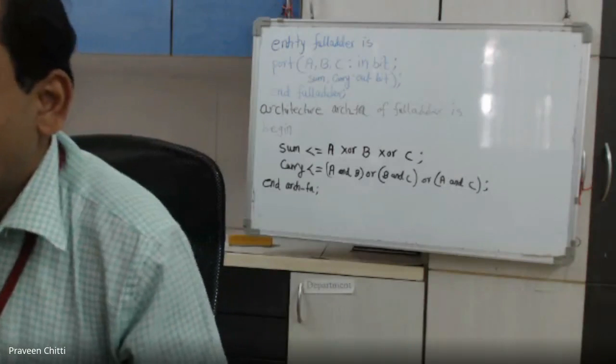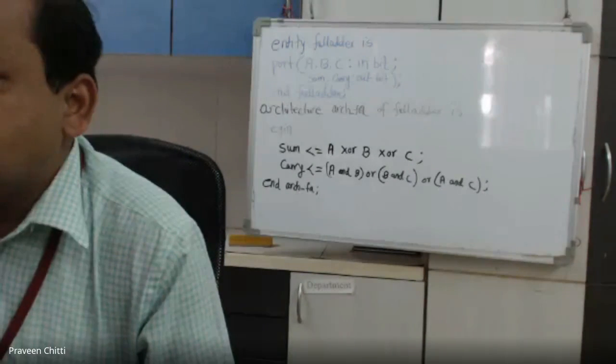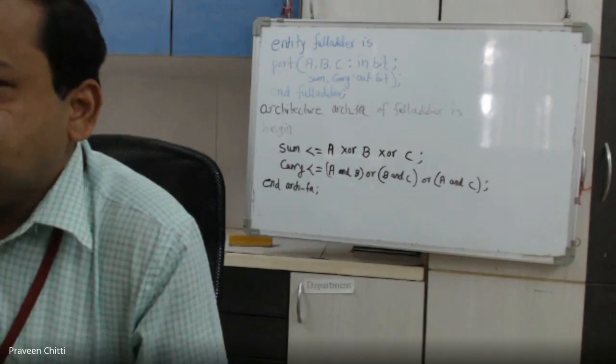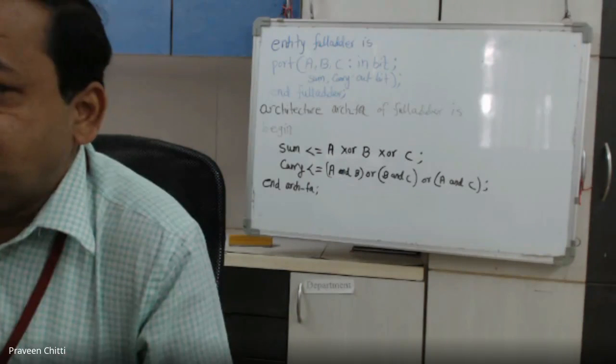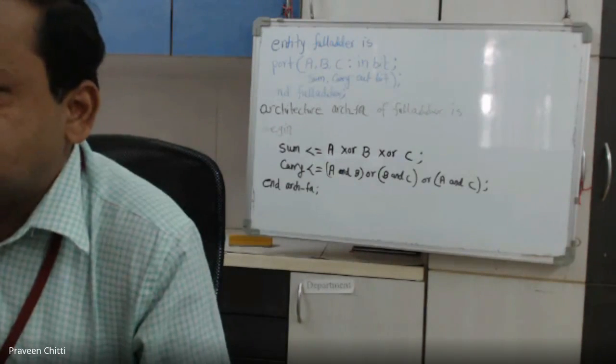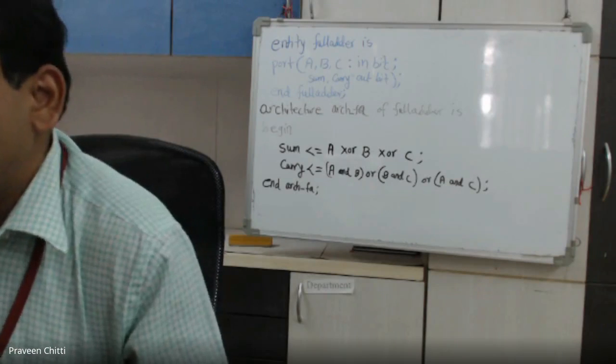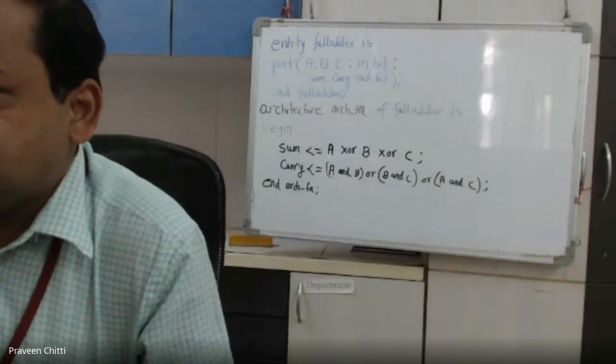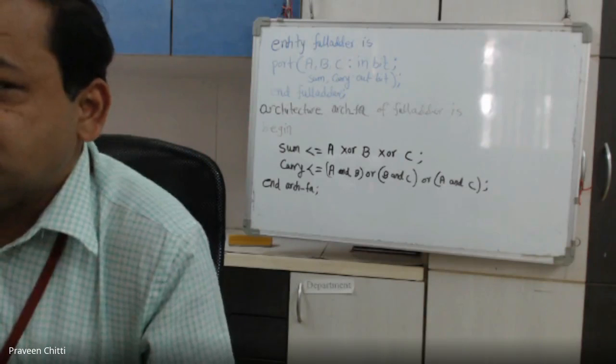Okay. So all of you have written the entity. Then after that, you write end mux. After completing the parenthesis, you have to put the semicolon. Then you should write end space mux and again semicolon. Okay. Next, what should you write?